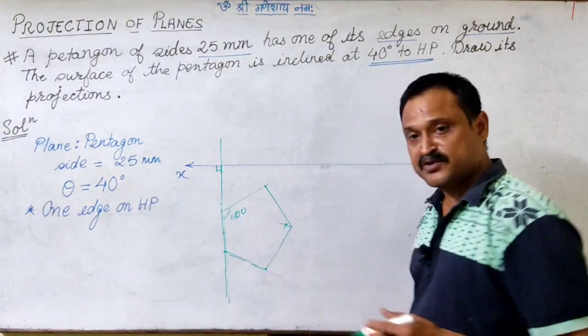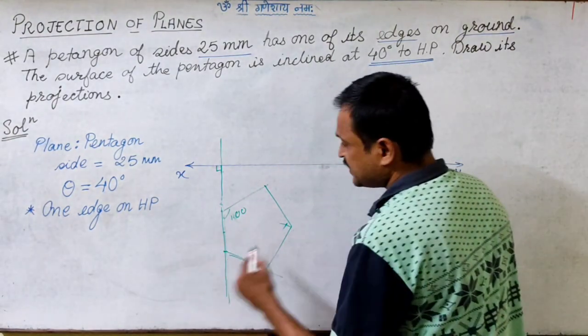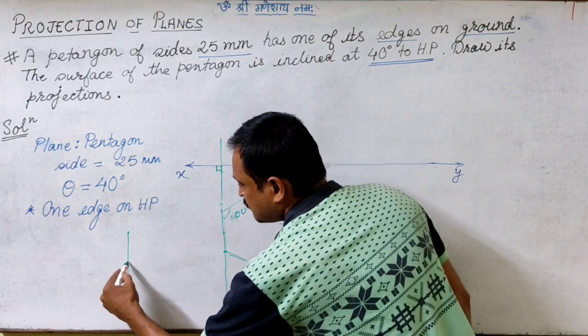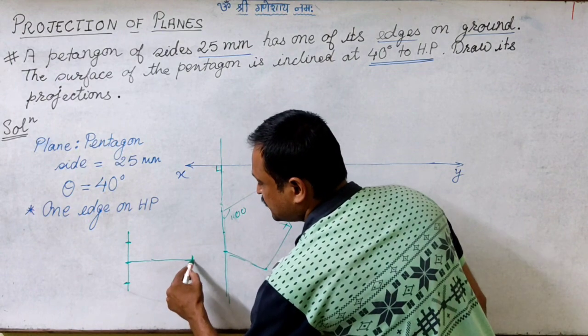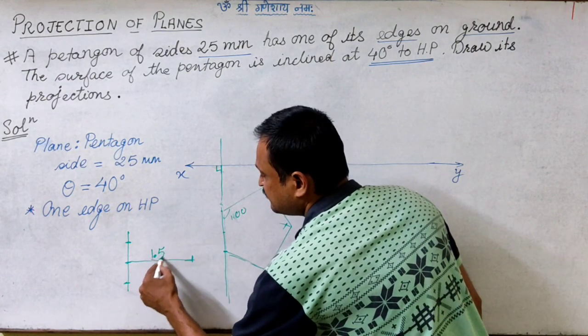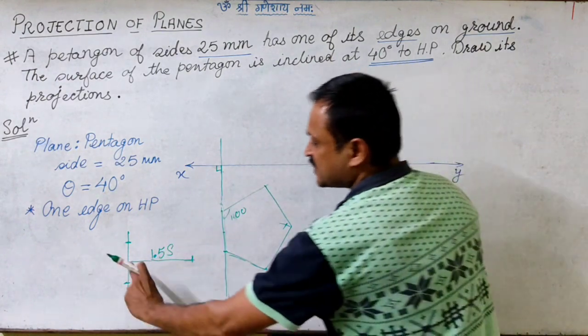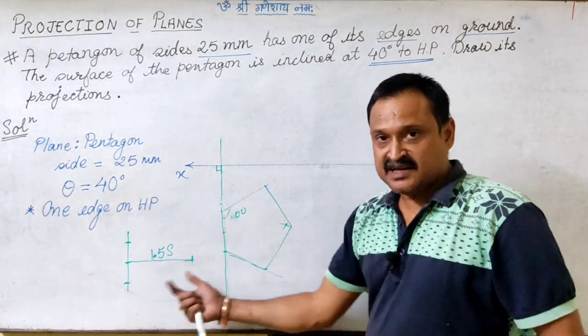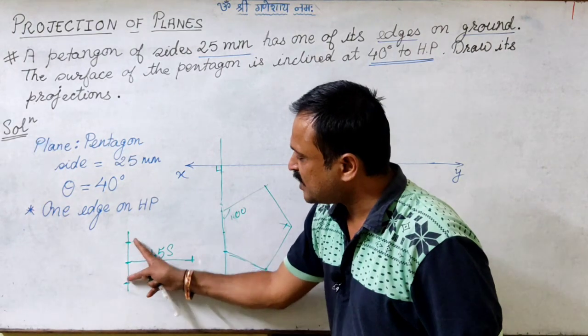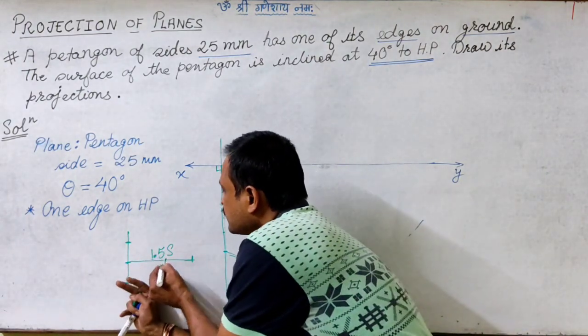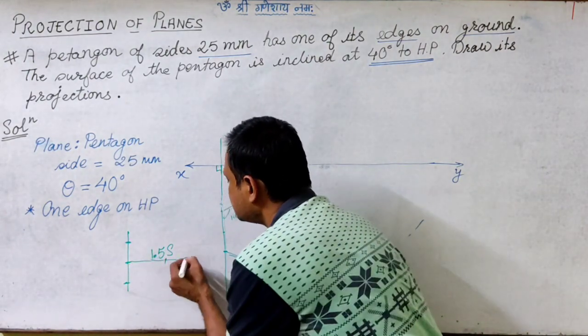Or otherwise, if I want to draw a pentagon, the opposite corner is 1.5 times the side length. So graphically, if I want to locate this corner, I can mark the midpoint. So 1, then 0.5 in the compass and I mark it.